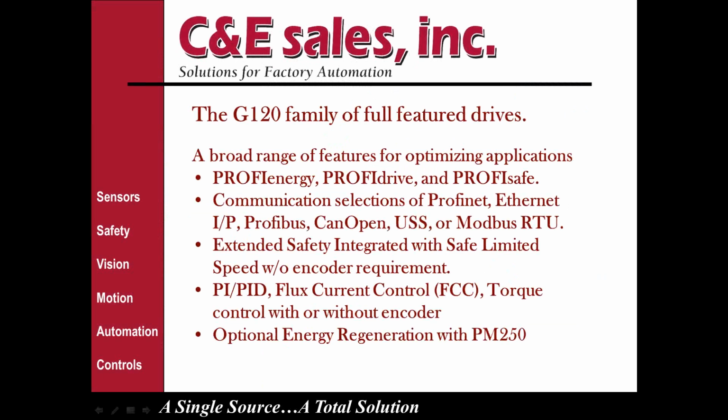The G120 has a broad range of features for optimizing applications. We mentioned Profi Safe earlier and Profi Drive. We also have Profi Energy, which is an agreed upon format for monitoring parameters of the energy consumption. And there are HMI applications and PLC applications that communicate with the drives and pull that information out so it can be readily displayed, recorded, and passed on to monitoring.